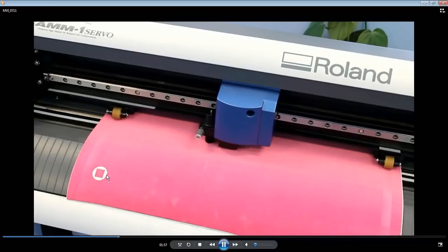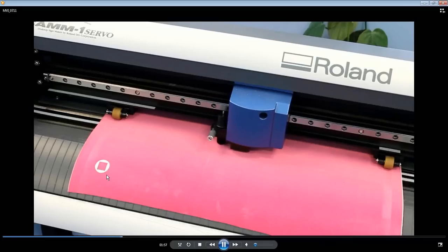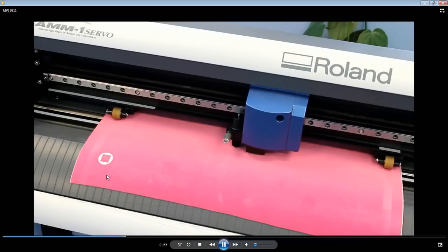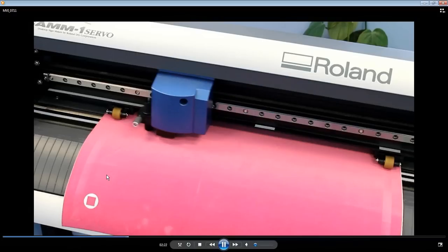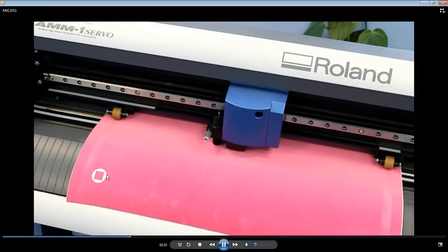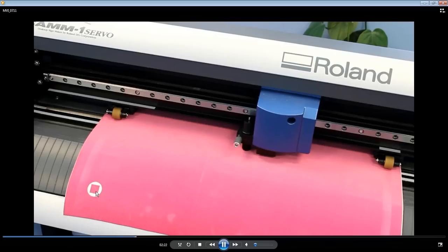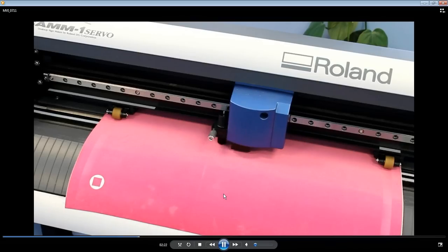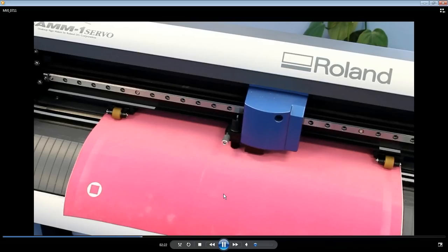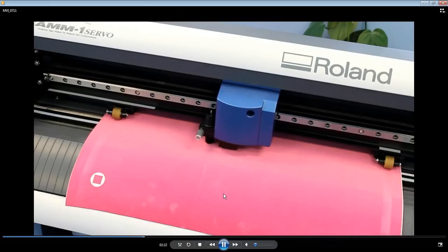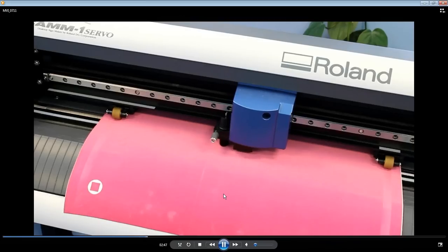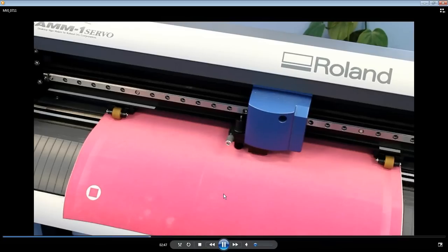It'll vary based on how new the blade is, or how long it's been in use, how dull it is, but you should always, always, always, when you put in a new media, do a test cut on that media. It's extraordinarily important to make sure that you're getting a good, clean test cut. Nothing worse than forgetting to do that, running a big design, and you know, some of these materials can be fairly expensive and some are not so expensive, but anytime you're doing something like this, it really hurts to have a whole bunch of media come out and you find out that your cuts weren't accurate just because the cut force was off and the design's not complete. Especially something like this where you've got a whole bunch of little holes that we have to work with. I want to make sure that my cuts are complete.